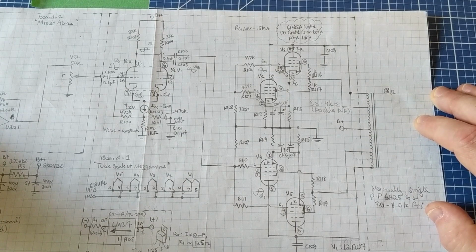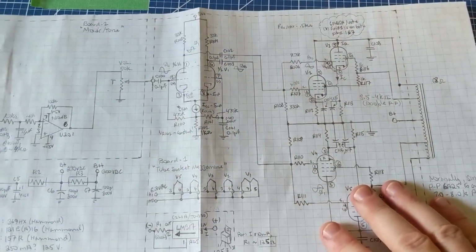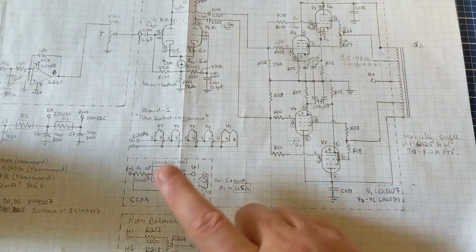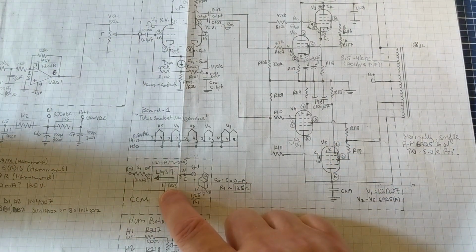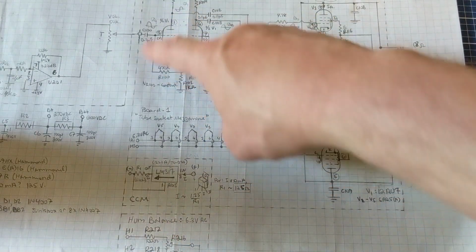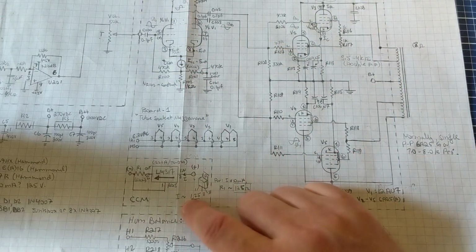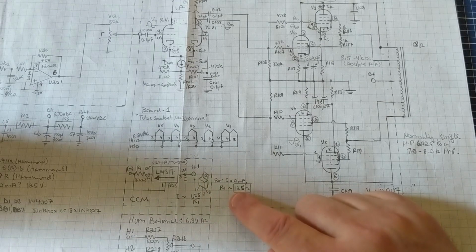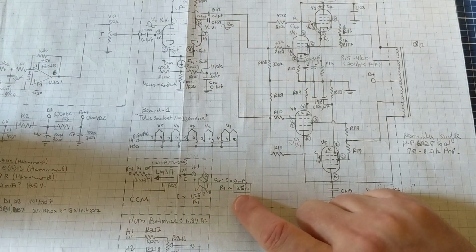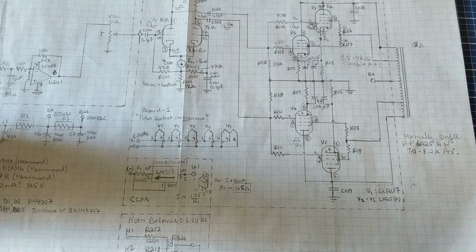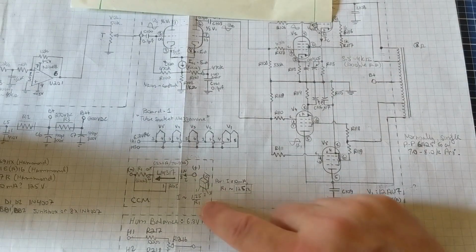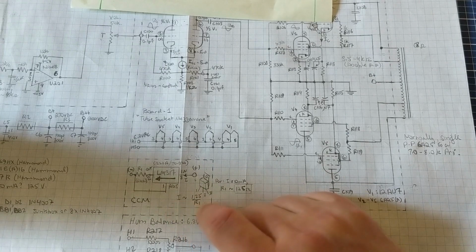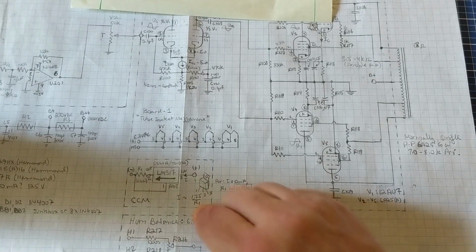So that's basically it. I guess the wrap up would be just to take another look at the constant current source. That was similarly explained in the other schematic I used for determining resistor values for this. Just as I said before, it's just a 317 linear regulator, and there's a formula that you can use for these. Let's see if I can find it. Yeah, the formula here is I is approximately 1.25 divided by R1.